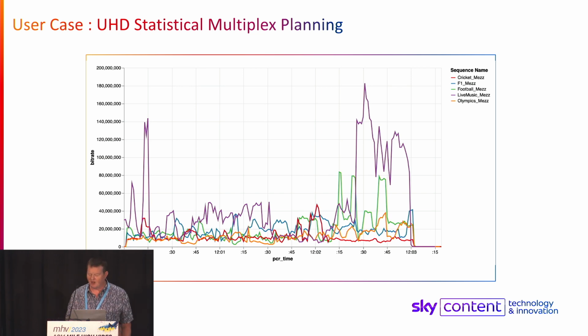In this scenario, we're tending to only use low numbers of channels for UHD StatMux, but the more channels you have, the greater the saving, because there's more potential saving across the various content types. With 2 channels, you get a moderate saving. Up to about 8 channels, you get a very good saving.